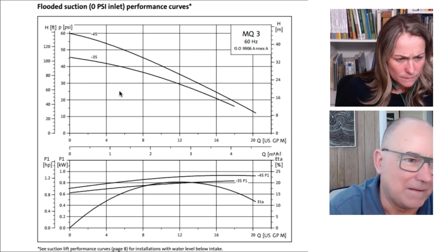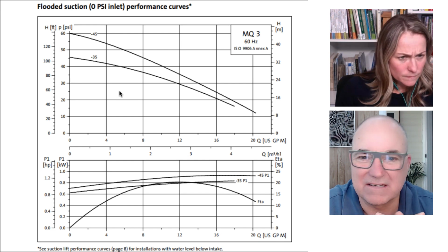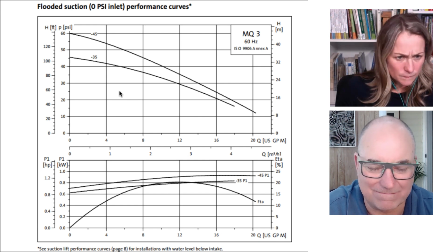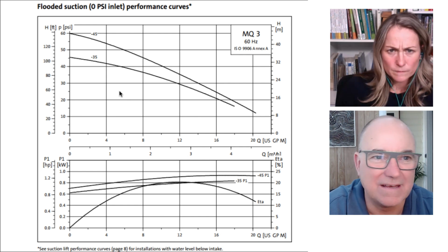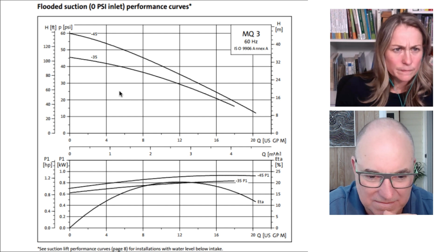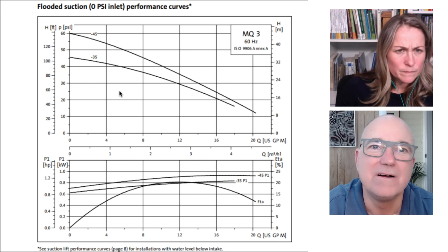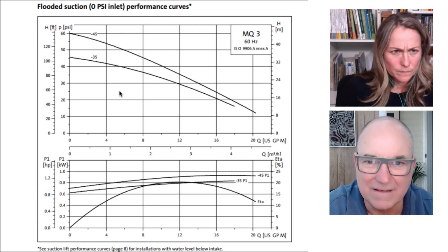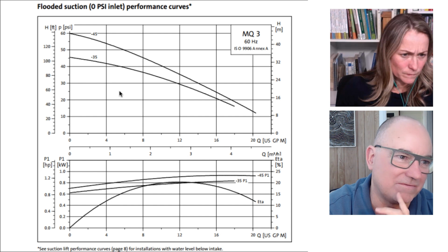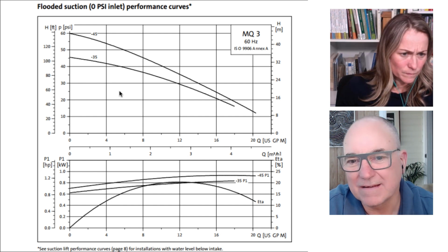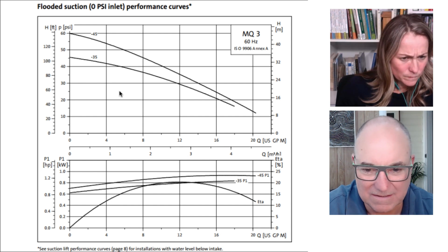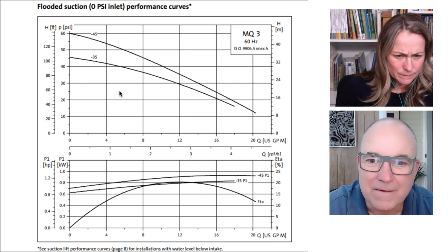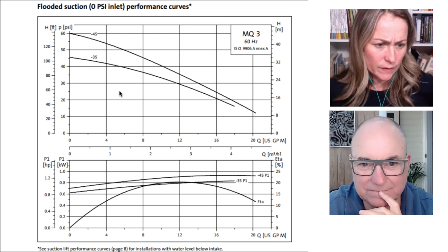You don't need a very big pump for that rainwater installation you were talking about. Like, this pump will do the job. It'll just be oversized, but this will help people because manufacturers tend to point rainwater harvesters to very big pumps, and that can be counterproductive. However, we've now given people a tool to find a pump that suits them. Don't choose one that's too small, obviously. So if one is slightly larger than you need, which it's likely to be, that will be okay. So yeah, exactly. All right.